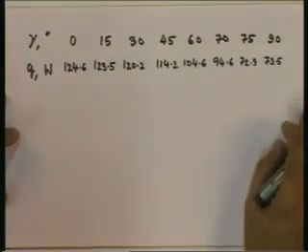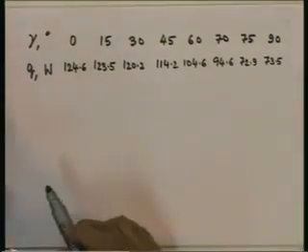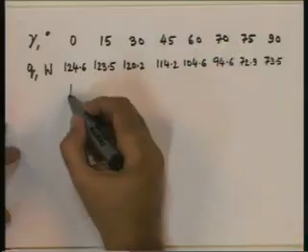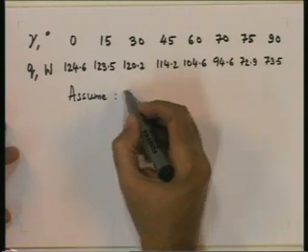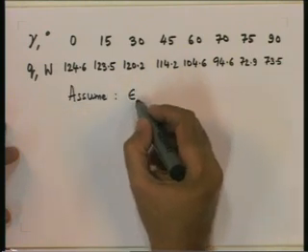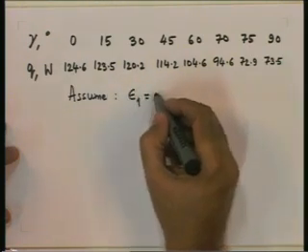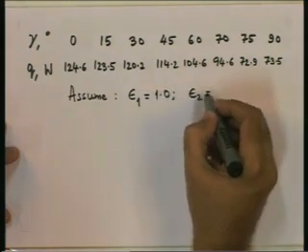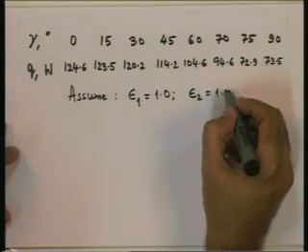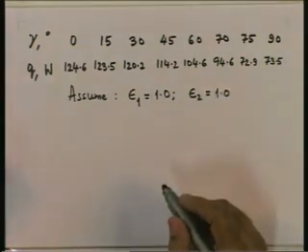How does this compare with radiation? Remember, in any natural convection situation, radiation plays a dominant role. So let us assume that for the plate surface the emissivity is 1, and for the glass surface also the emissivity and absorptivity are 1.